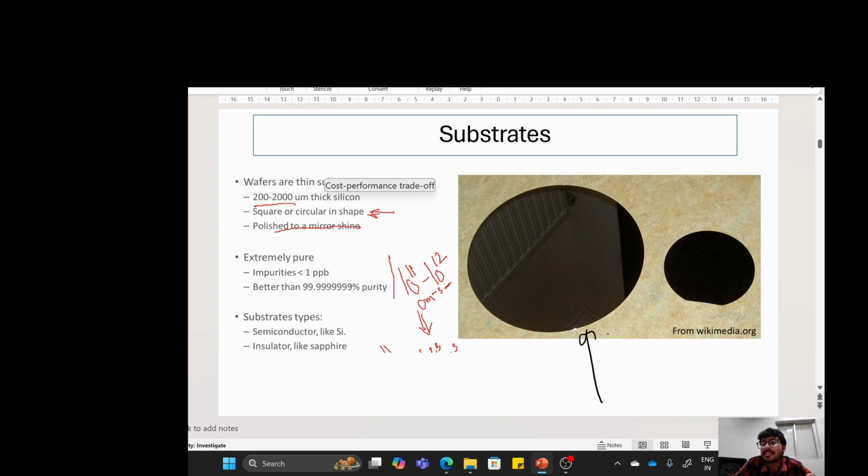These are the desired substrates because there is an advantage of using silicon: a very good interface of silicon dioxide, and good tunability with doping. You can tune the conductivity of this material, you have very good control, because over the years this is a highly mature technology.